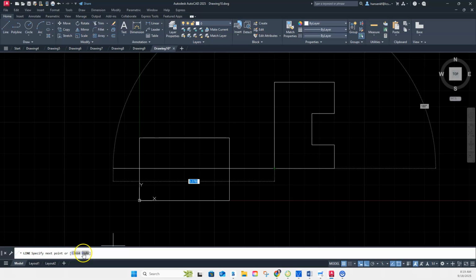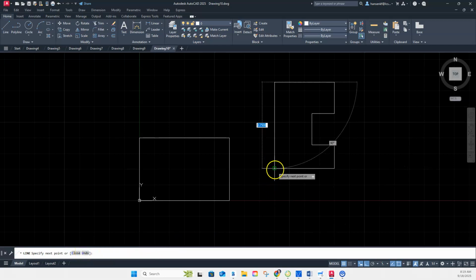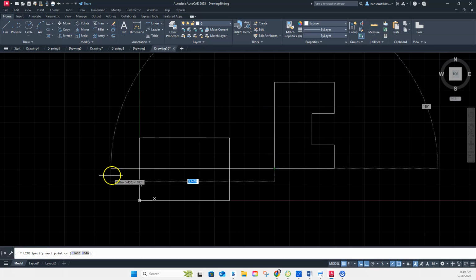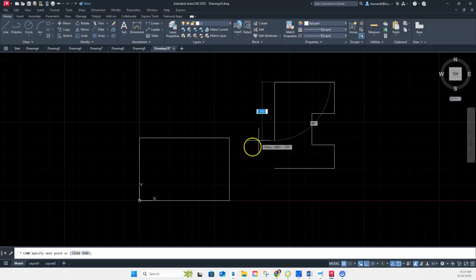It is important to know that the undo button is something that you can use to back out through a step. If you don't, you go over and click the undo button in the command line. You can simply type in U, and it will also back it out. So I'm just typing U on my keyboard and hitting the enter button. So those are the basic features of the line command.